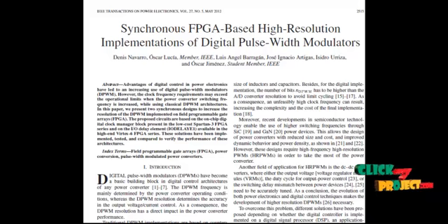A lot of different delay line architectures have been proposed in recent years, and even a classification of them has appeared. Although all these architectures differ from each other, almost all of them make use of delay lines. The advantages of delay line DPWMs are high resolution and low power consumption. However, they have lower linearity and sometimes non-monotonic behavior. To obtain a trade-off between the advantages of counter-based and delay line DPWMs, hybrid architectures have been proposed. The higher the number of bits in the synchronous part, the higher the linearity achieved.